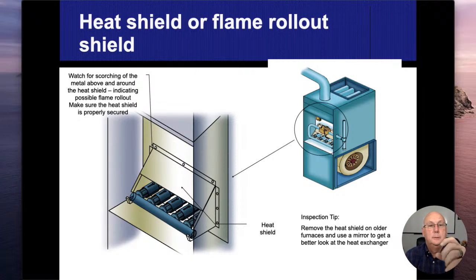I'm going down memory lane here. I used to have this little dental mirror when I started, and I would aim it because right up on the underside or straight in the back, that's where you would find most of the holes and rusted out parts of the heat exchangers. And once the heat exchanger is gone, you're done. You might as well just get a whole new furnace.